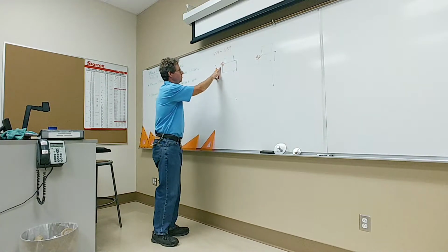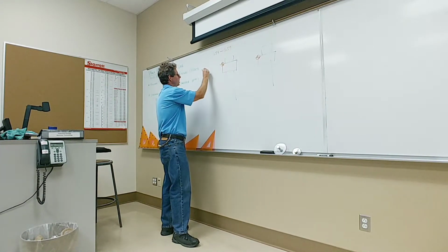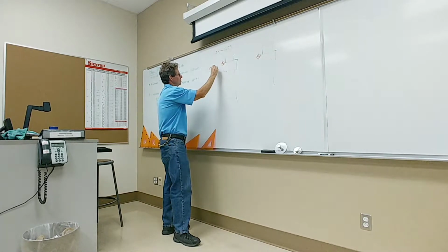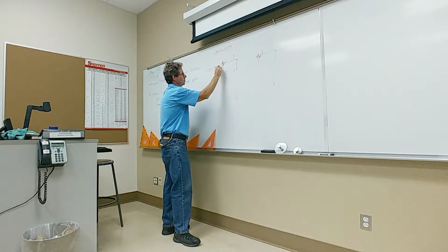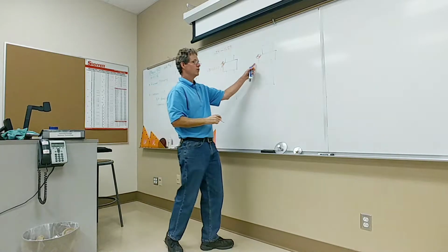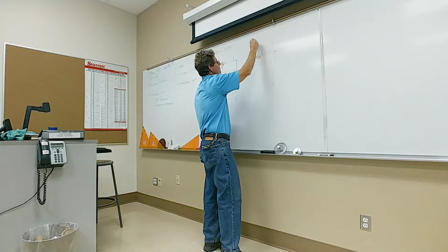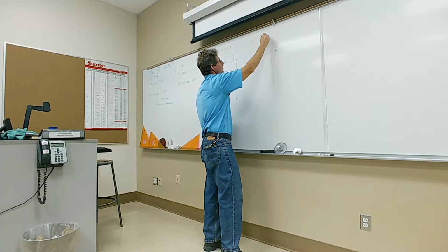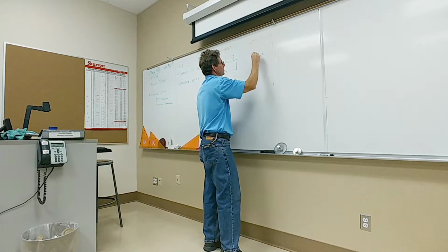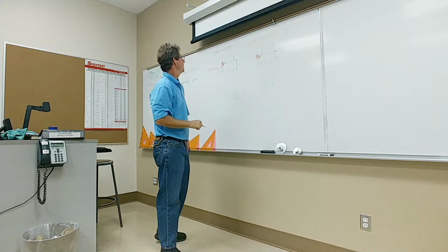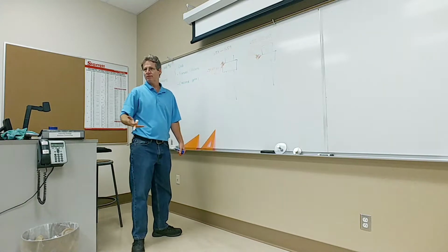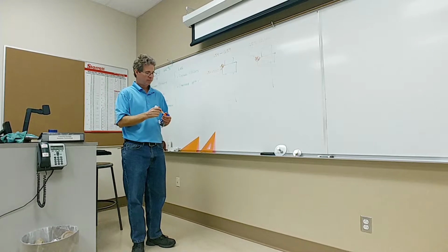So the way we would identify this, if this was our first part, we probably would say this is our G54, X0, Y0 coordinate. Okay. If I had this part set up, I would maybe call this my G55, X0, Y0 coordinate. Okay. If I had other parts on my table, I can call them G56, G57.